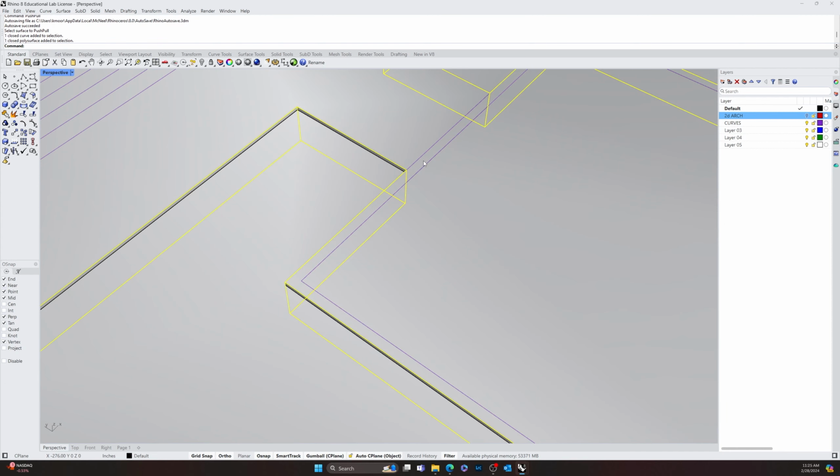So you want to see it again? Let's do it again. So I already did the math. If I do 9-inch risers on a 24-inch step, it will go up perfectly this dimension, this amount of steps to get to a 14-foot high level. So you have to do that math first, okay? That's how I know how many of these to do, and that's how I know this distance right here. Basic math. Okay, so array, curve, select the object to array, enter, select the curve, and then the item distance, the number of items, 20, and then we hit enter.